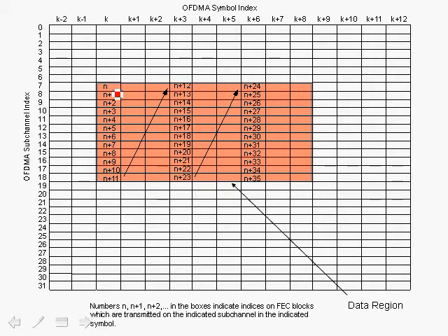Here is a very important point. You'll notice that N indicates what we call an FEC block. So an FEC block contains the data for one forward error correcting block, and it spans 3 OFDM symbols and occupies one subchannel. So this is very important. So here we show a subchannel, and within that subchannel there are 3 OFDM symbols, and this constitutes an FEC block for forward error correction coding.